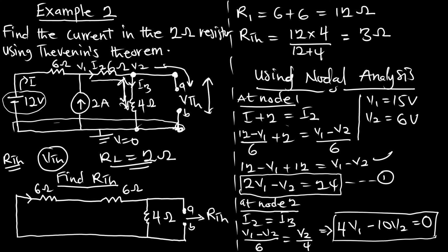And what do we know about parallel voltages? They are equal. So we can say that V2, the voltage across these 4 ohms, which is measured as V2 and is 6 volts, is equal to, this is also what? Parallel VTH. VTH, and that is also equal to 6 volts. So our V2 is equal to VTH, which is 6 volts.